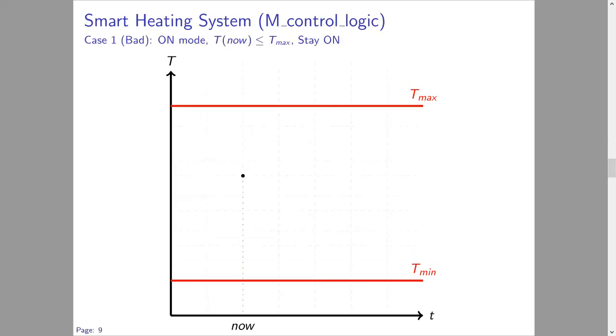In the next refinement, we aim to concretize the discrete control by specifying that when certain events are detected, what action should be taken. The key problem is what kind of events to detect. Taking our heating system, for example, an intuitive design is that if we are in the on mode that increases the temperature, and the current temperature is less than or equal to Tmax, then we decide to continue increasing the temperature for the next cycle. This design attempts to detect the precise threshold to react, which would be fine if we were sensing all the time.